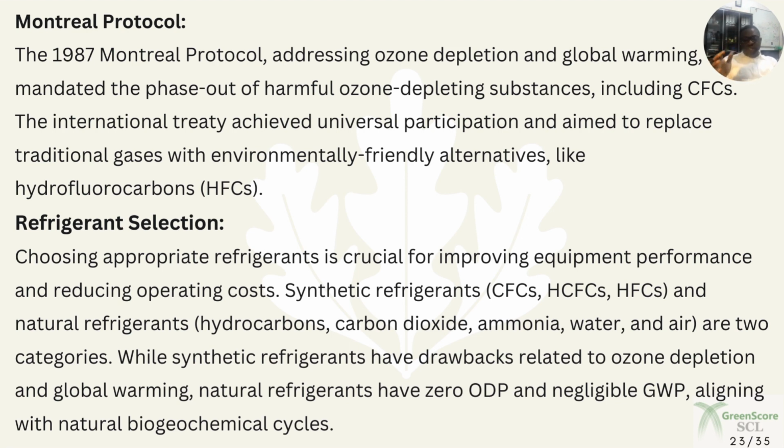Alright, so this is what makes the issue of refrigerant selection very important. This is primarily about choosing appropriate refrigerants for improving equipment performance and then reducing operating costs. Synthetic refrigerants, the ones that are not natural, like the CFCs, HCFCs, and HFCs, and natural refrigerants like hydrocarbons, carbon dioxide, ammonia, water, and air are two categories of base refrigerant.